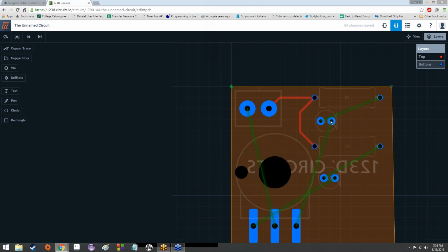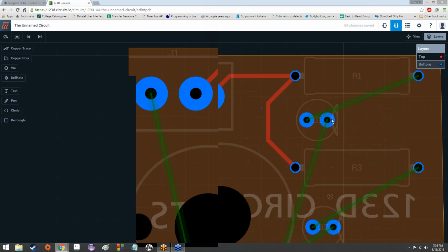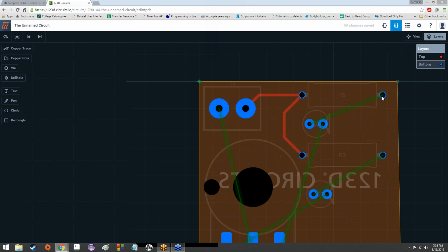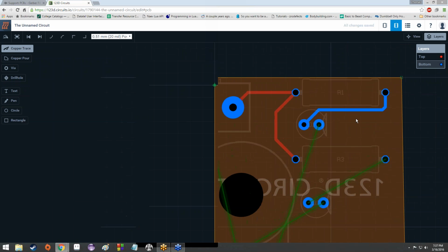Undo. So as you can see, I got a yellow area there, which means that there is overlap where there shouldn't be, or there's some sort of error with the PCB design that we have. In this case, it was overlapping with the other hole on the LED, creating a connection where there shouldn't be one. See, I updated it though so that it maneuvers around that connection. So now there's no issue.